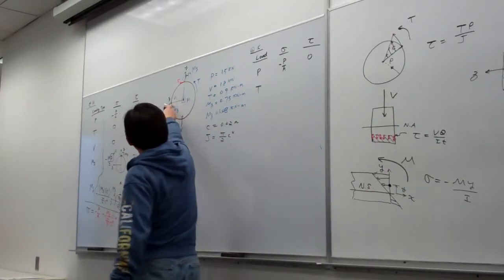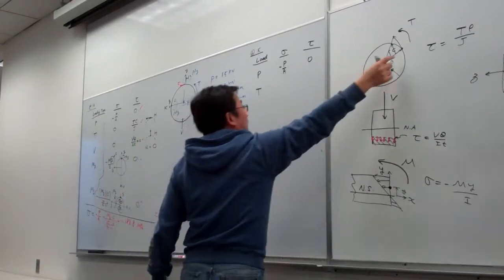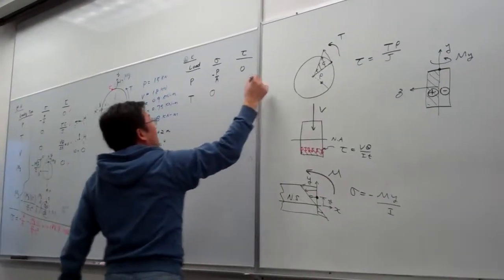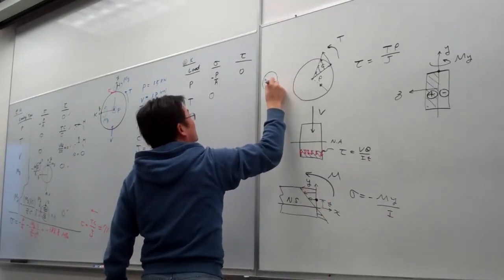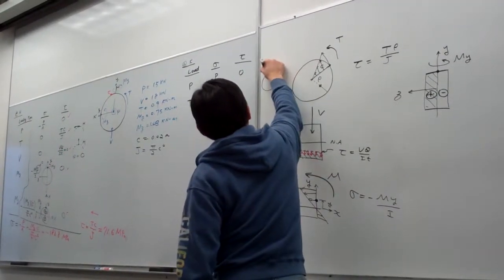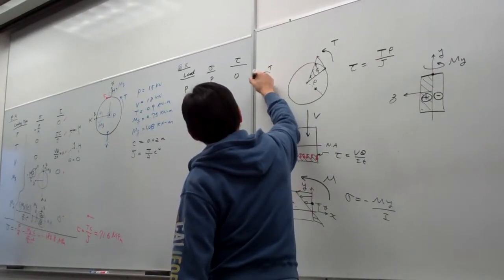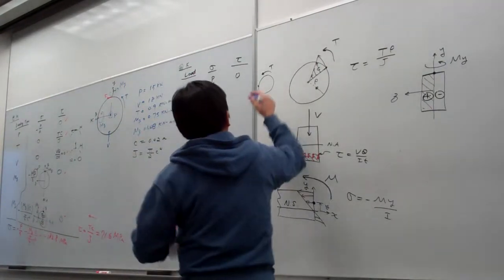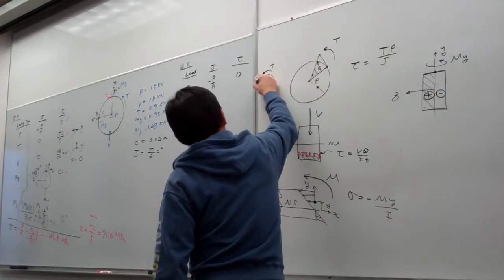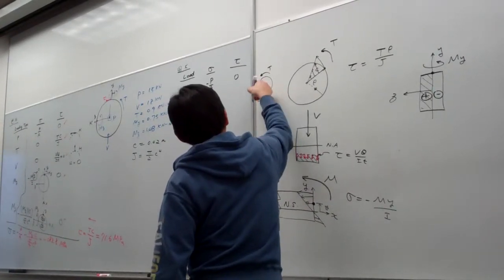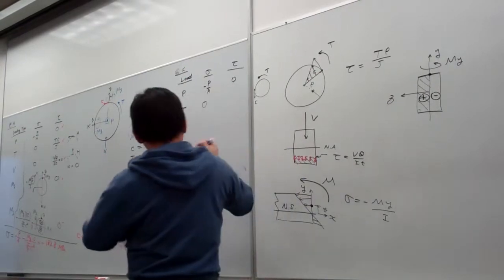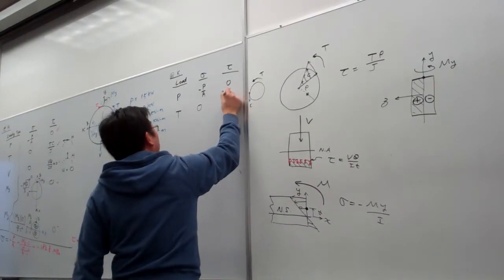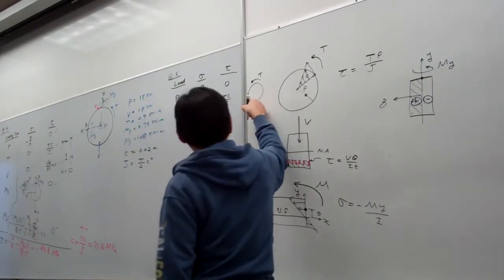Now at this point, you can see using our concept here, the shear stress at point K, let me draw this one here. So now this is our cross section, and our T is in this orientation. The point K is here. So that means that the torsion will induce at point K a shear stress, the direction of the tau will be in this direction. Right? Okay, so tau equals Tc over J, and the direction is downward as indicated.